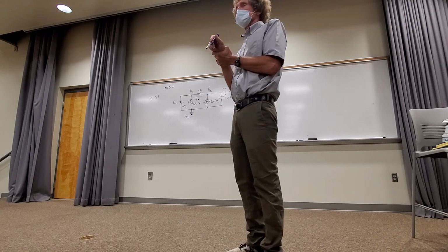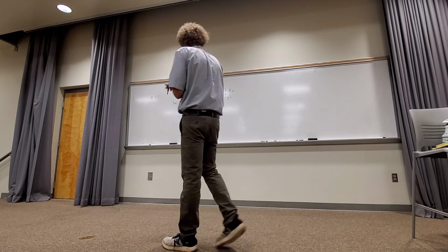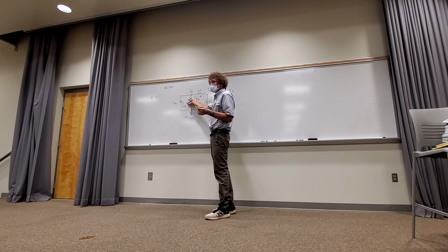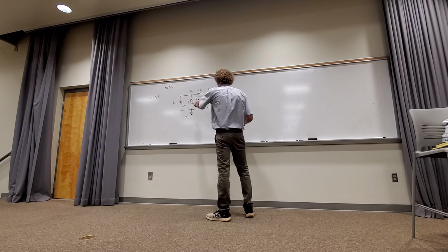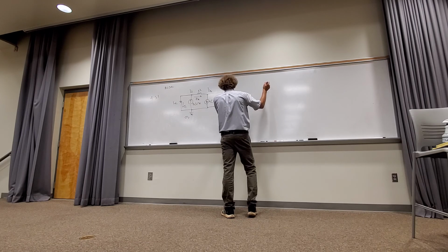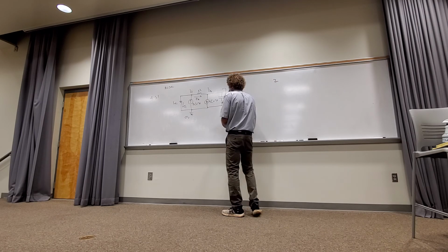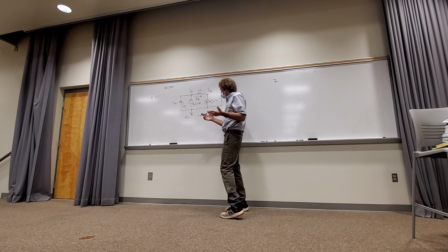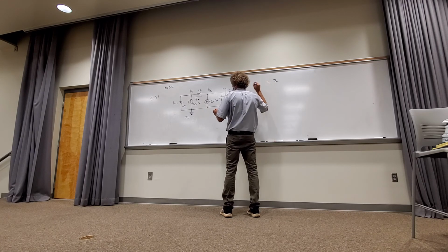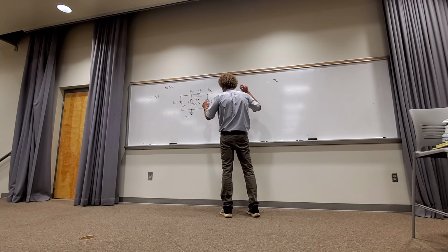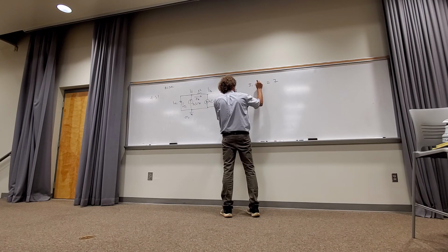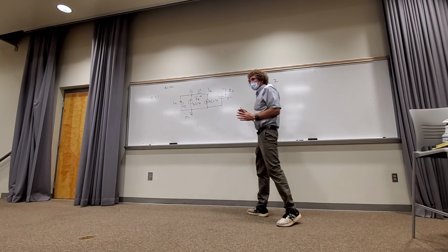As before. All right? Now we write current equations for this first node. Can y'all see it okay? For this node, whatever comes in flows out. What flows in is 2 at an angle of 0 degrees, and I just put 2 because the 0 degrees doesn't do anything. Y'all follow me? Just put it as 2. And that's equal to the current leaving, I2 and I1, or I1 plus I2. Everybody follow me on that?